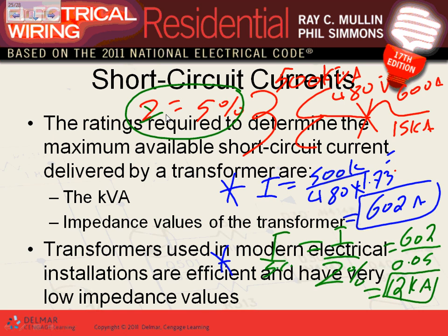The impedance of the transformer. Everybody knows what the impedance of a transformer is. Transformers are made out of windings. These windings make impedance. The manufacturers are smarter than Chad. They calculate this impedance and give it to you as a percentage. The higher the percentage, the more impedance the transformer has, and the less efficient it is. Why? Because if you have high impedance here, guys, there's a lot of current cooking inside the transformer, doing nothing, just being eaten, digested inside this transformer.